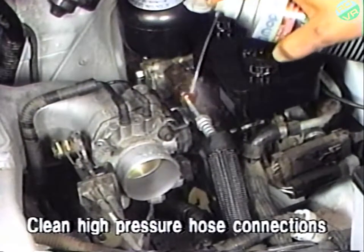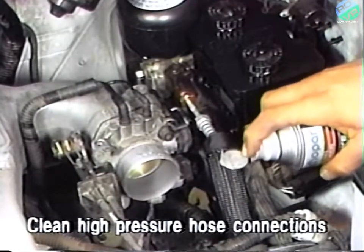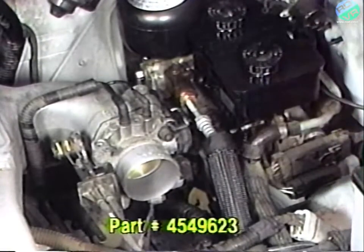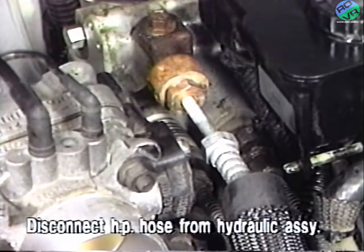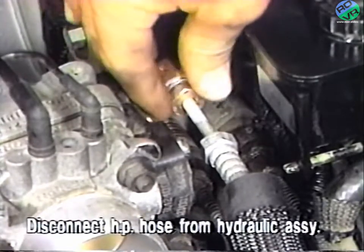Next, on all models, clean the connecting points for the high-pressure hose. Use Mopar brake parts cleaner, part number 4549623 or an equivalent. Now, disconnect the high-pressure hose from the hydraulic assembly. Be sure to wear safety goggles when disconnecting this or any other fluid lines.